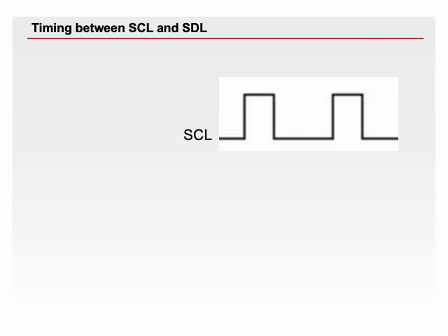Here we need to understand the concept of timing between the SCL and SDA signals. That is crucial for reliable data transfer. The timing is determined by the clock frequency and the data rate selected by the master device. During data transmission, the SCL line generates clock signals as shown here. For example, in the clock signal shown in this figure, we have two rising edges and two falling edges.